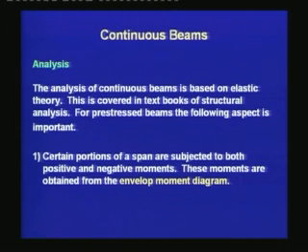For a simply supported beam, the span is usually under positive moment unless the effect of the upward thrust due to the prestressing force is high, but due to the external load the moment is positive.